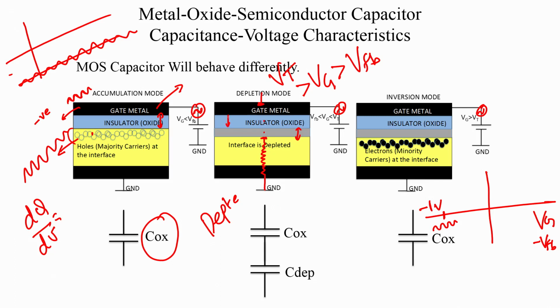You have the insulator capacitor and then you have the depletion capacitance, and we all know how to calculate the depletion capacitance by solving Poisson's equation. This region is depleted, does not have free carriers, you can imagine it to be another insulator, if you wish. So, you have a series combination of these two insulators. So, the capacitance now decreases, it is not only Cox, but it is a series combination of Cox and C depletion in depletion mode operation. So, that is the capacitance that you see.